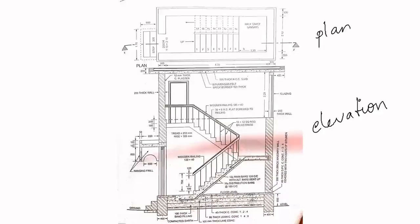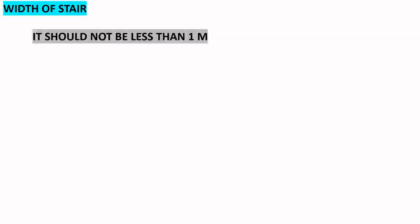Now, before going deep into our plan and elevation, we need to see some of the basic ideas about the dimensions. First is the width of a stair. It should not be less than 1 meter. The total width of the stair, that is the horizontal distance of the stair, should not be less than 1 meter.